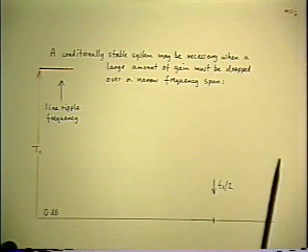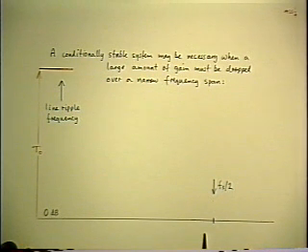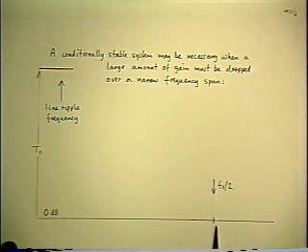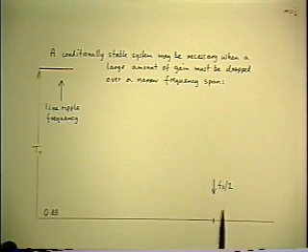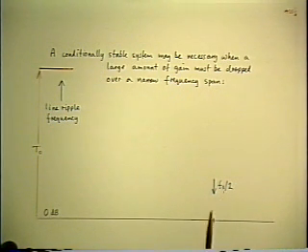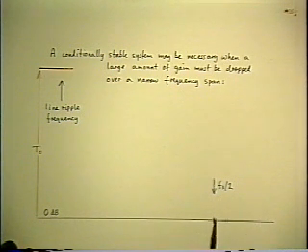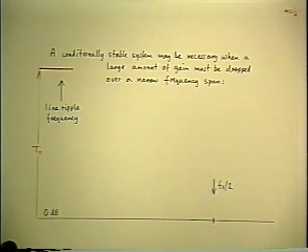In the case of switching power supplies, this upper limit to the window is half of the switching frequency. You have to cross over loop gain below Fs over 2 to avoid a special kind of instability resulting from the fact that the switching frequency is in there all the time. And if you have a loop gain bigger than 1 at the switching frequency, of course it's going to drive itself directly into oscillation.